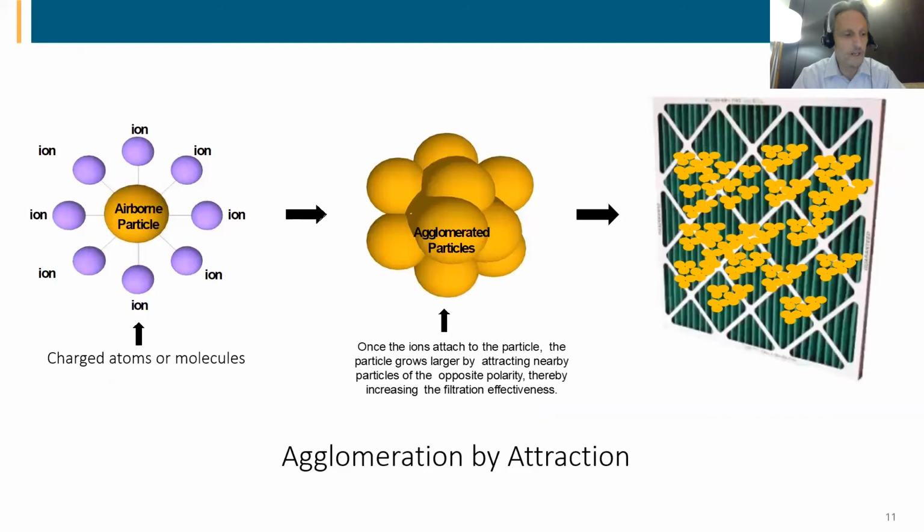Let's talk a little bit quickly about what ionization can do to clean the air. I told you it does. I will now tell you how it works. As I mentioned, what I am doing with needlepoint bipolar ionization is simply imparting a charge of energy, both positive and negative electricity, to the atoms and molecules in the air that cross over the device, that go out through the ductwork, that go out through the registers and grills and enter the space and mix with the issues of concern, the particles in the air that are there.